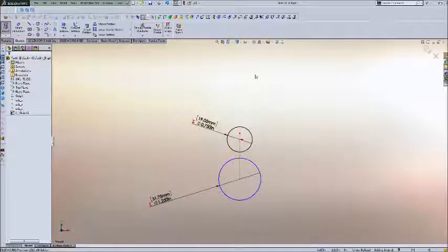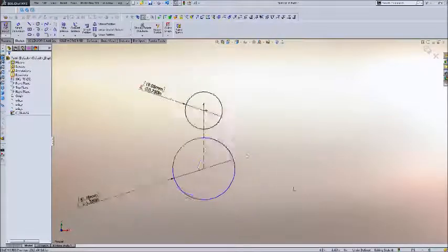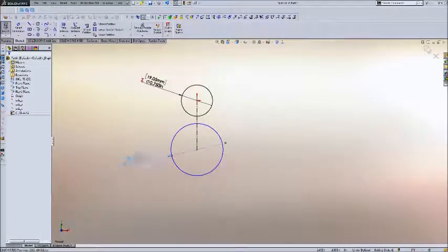And in order to account for that in design, what I do is I add about 2 to 3 thousandths into the center-to-center distance, and that's what that center line is. Center-to-center distance of the two gears. So how to find the center distance of two gears, there is an equation for that, and I'll be putting that in the description of this video as well.